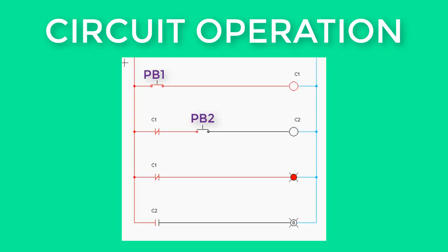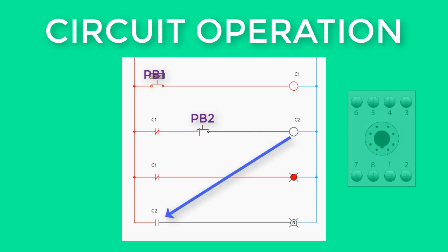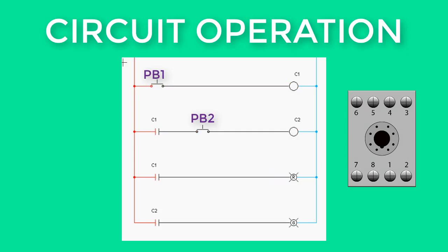Control devices, such as switches or push buttons, can be placed in series or parallel. Computer circuit design allows for an infinite amount of both normally open and normally closed contacts. In actuality, a relay has a limited number of contacts. The designer must allow for these limitations.